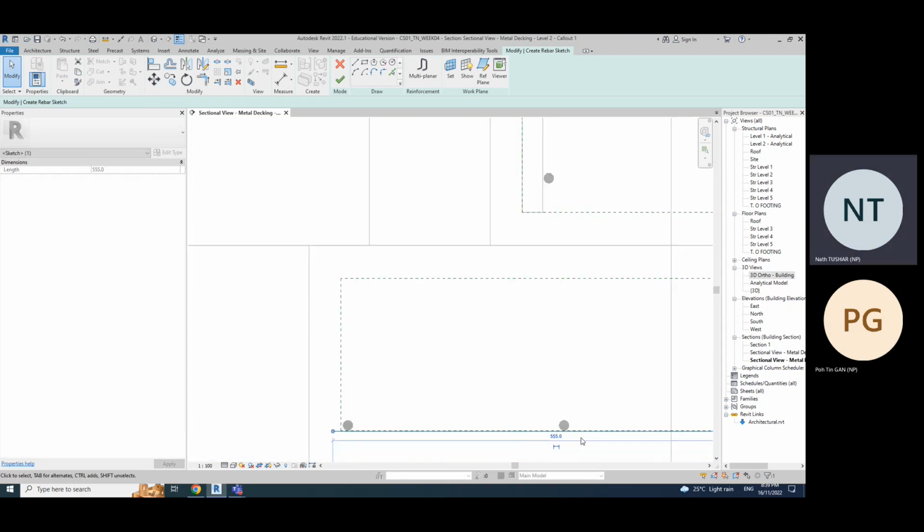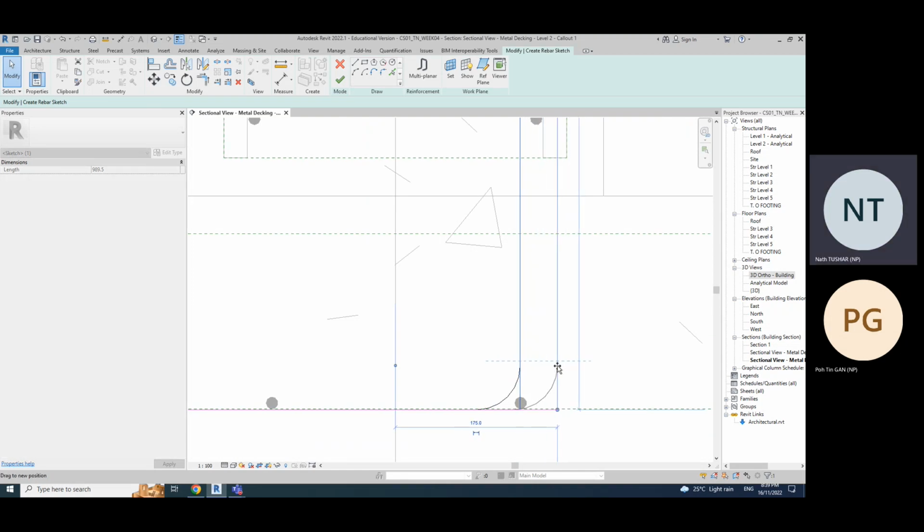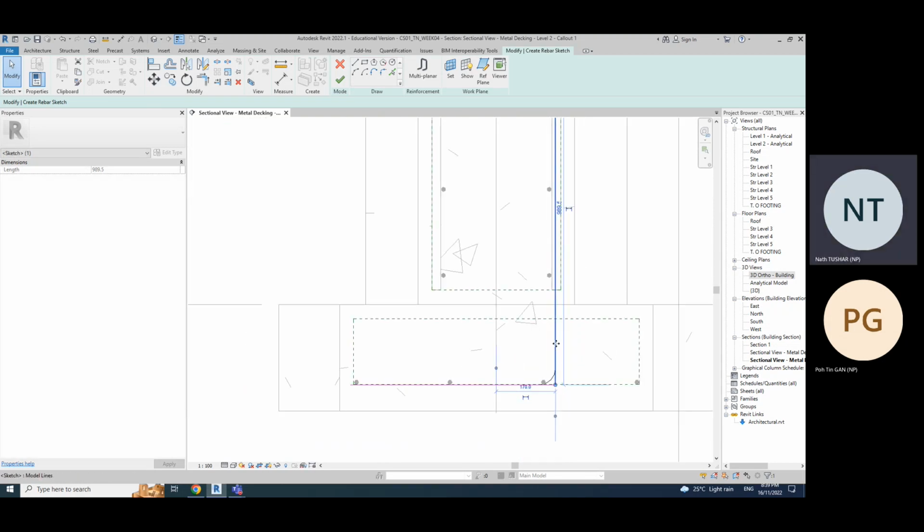The bottom should touch. And this rebar that I have over here, my hook should go somewhere like that, correct? But as you can see, if I do my hook like that, this rebar over here is intersecting the rebar that I drew last time.